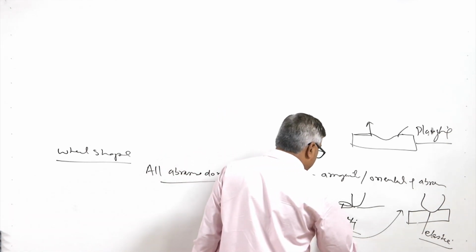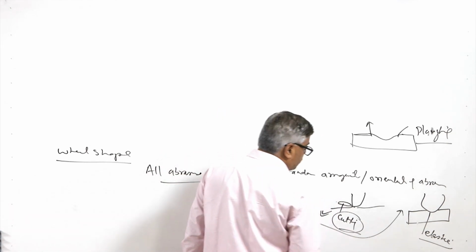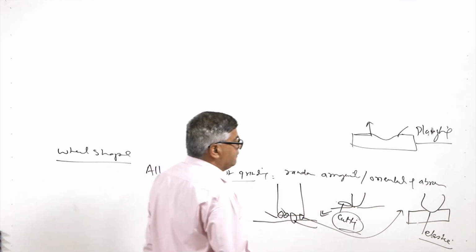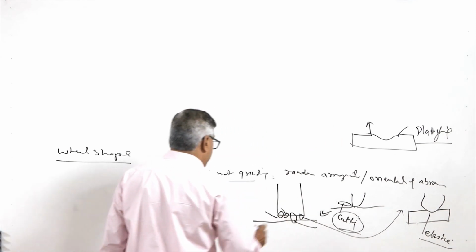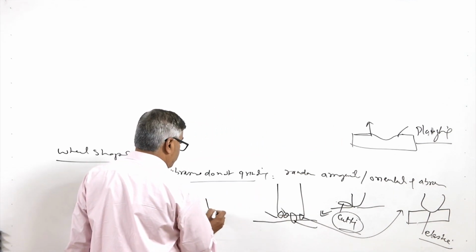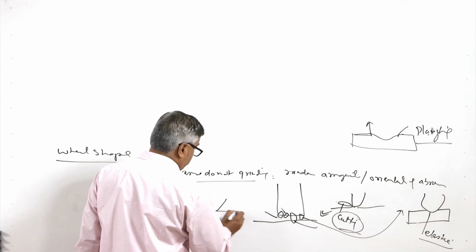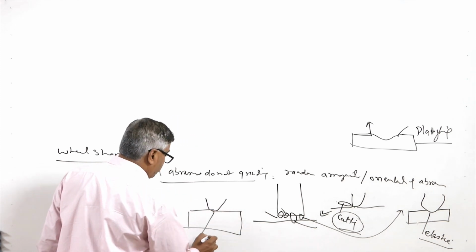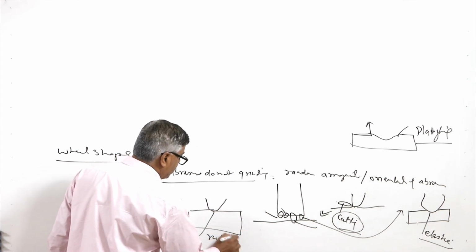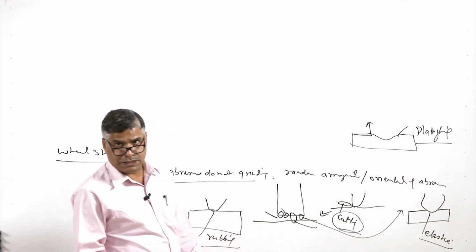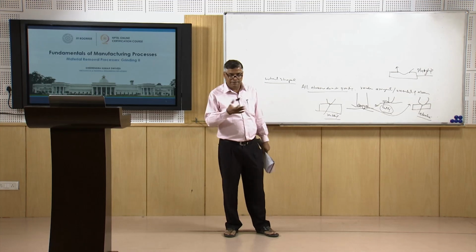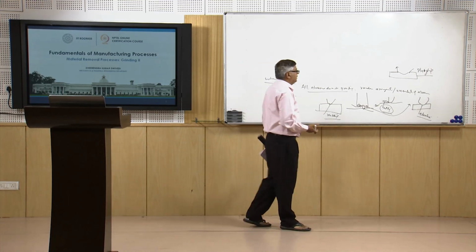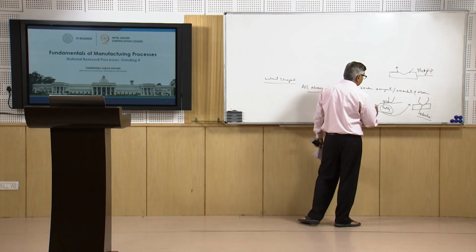So ploughing is a kind of plastic deformation by displacing the material sidewise but not removing it. Grinding is basically performed in the case when there is cutting. In ploughing there is no cutting, just displacement of the material, and in the third stage the abrasive just touches the surface of the workpiece, so it is performing just rubbing. Depending upon the extent of projection of the abrasives from the surface of the grinding wheel, that determines how the abrasives will be interacting with the workpiece.